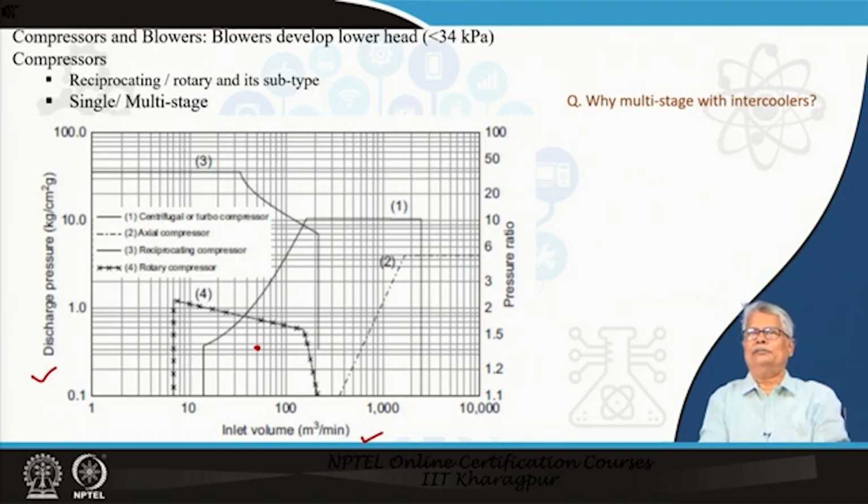Now, if I look at compressors particularly, you will see that most of the compressors that we use today are multi-stage. The simplest and the most common compressor you must have seen is in a motorcycle repair shop or a cycle repair shop, which compresses air. Let us have a look at the components of it. It is a reciprocating compressor. So, there is a piston which is sliding inside a cylinder with valves. The suction is from the ambient air, and the discharge goes to a vessel which is called a receiver.